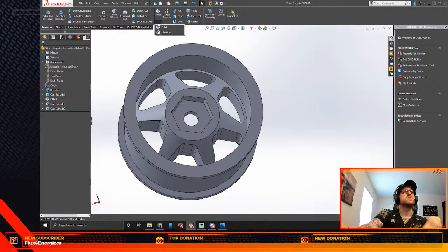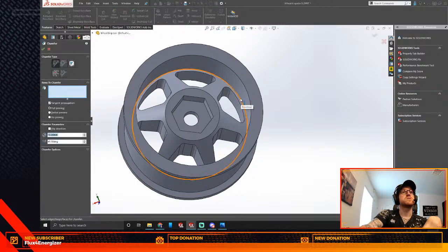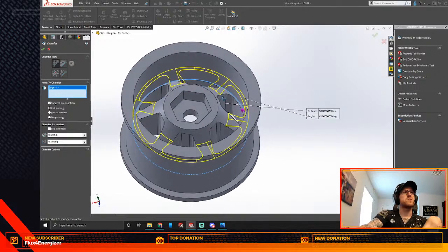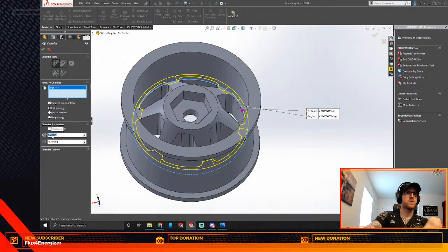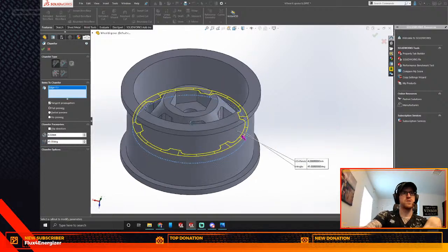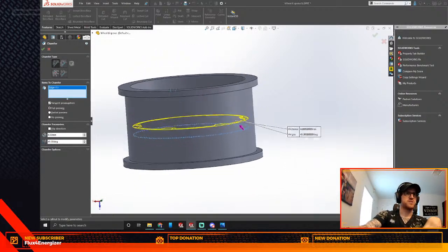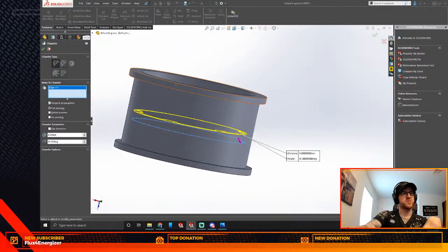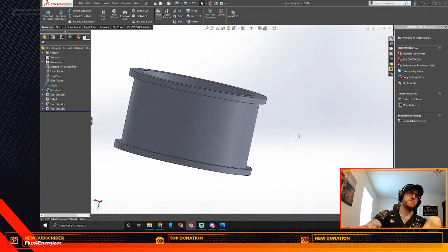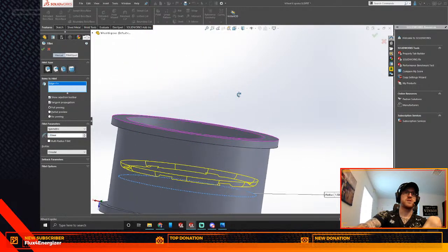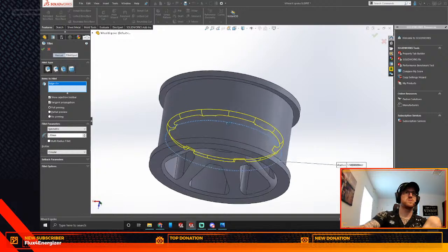So we can go in and chamfer, hit that guy. Now we can thicken it quite a bit, but we don't need it that thick. That's kind of nice, but chamfer, probably not the best to do for that one. Let's do a fillet. With that, okay, that looks cool.